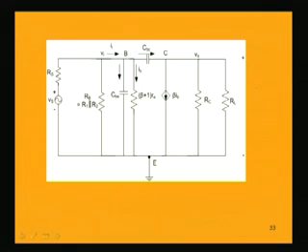In order to analyze a circuit, it is better to have the input and output circuits separated out, but here the problem is coming because of the shunting capacitance between the input and output, that is base and collector. So, if somehow we can simplify this circuit further by separating out the input and output circuits, then it will be better for our analysis.